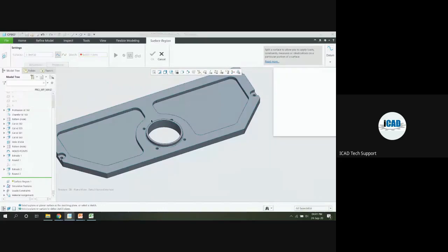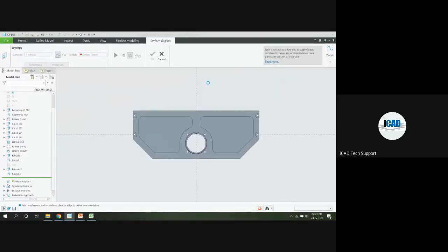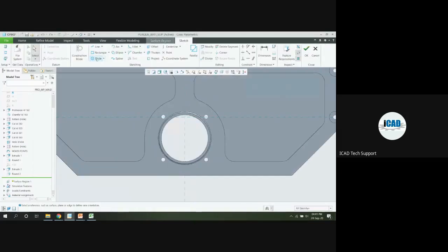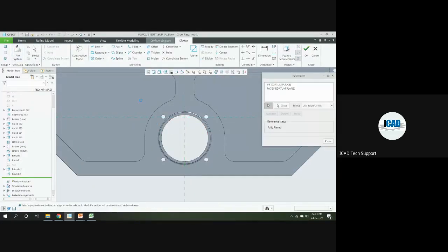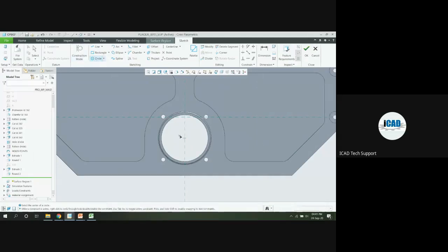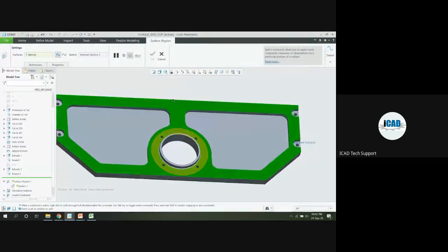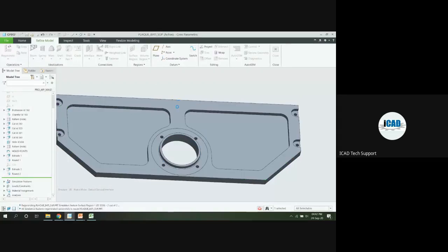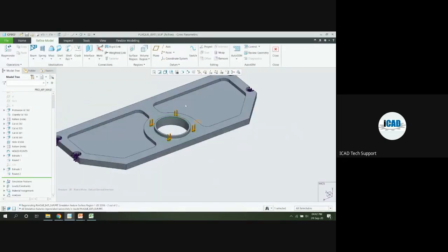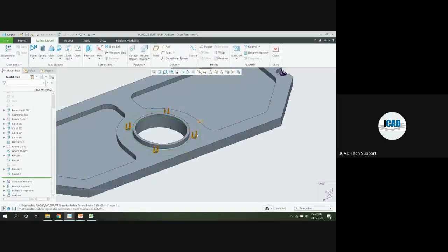In references, we can define the specific load area. Giving the reference, on the specific area I want to apply the pressure load. It will behave as a separate surface region.